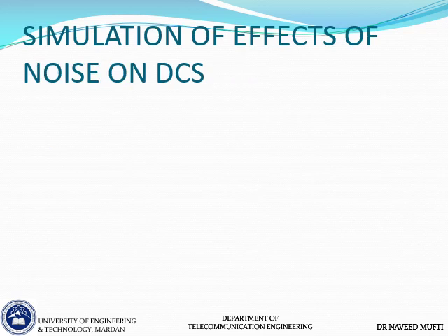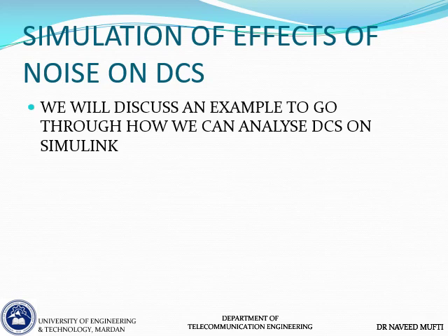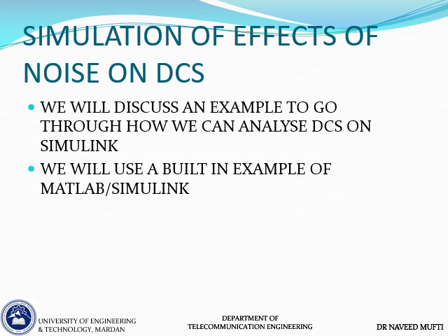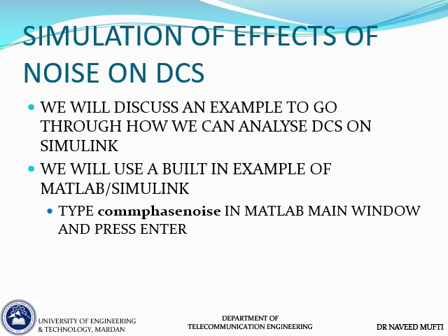So what we are going to do firstly in MATLAB or Simulink is look at the effects of noise on a digital communication system. We will discuss an example to go through how we can analyze a digital communication system on Simulink. For that, we will start off with a built-in example in MATLAB Simulink, which can be activated if you type commphasenoise in the MATLAB main window and press enter.